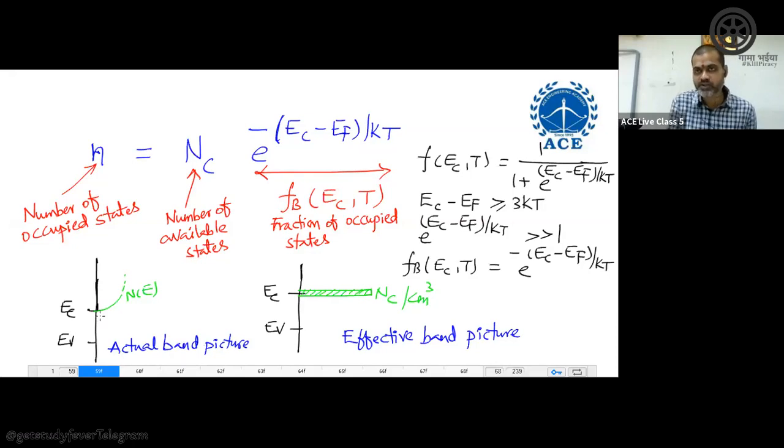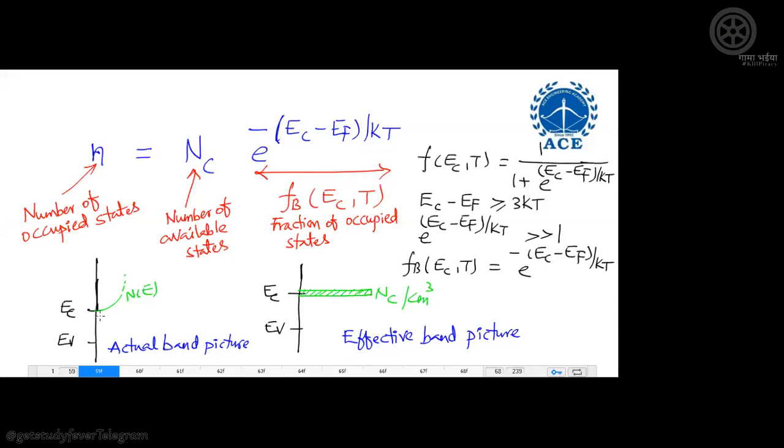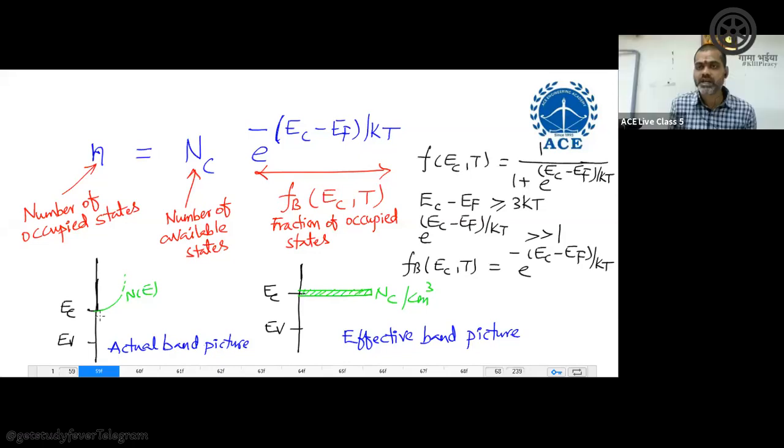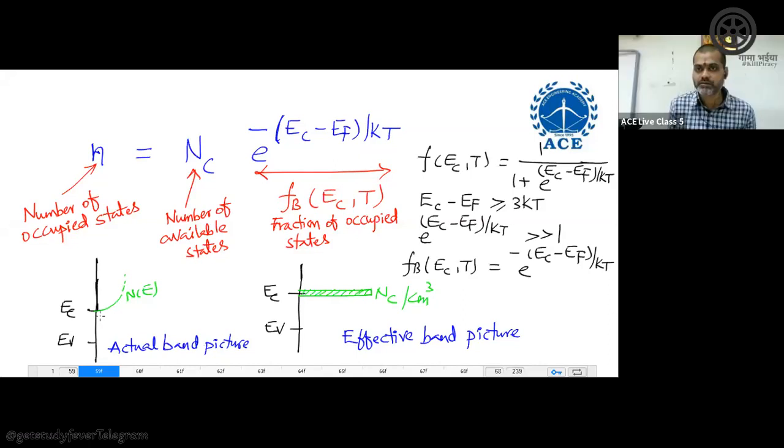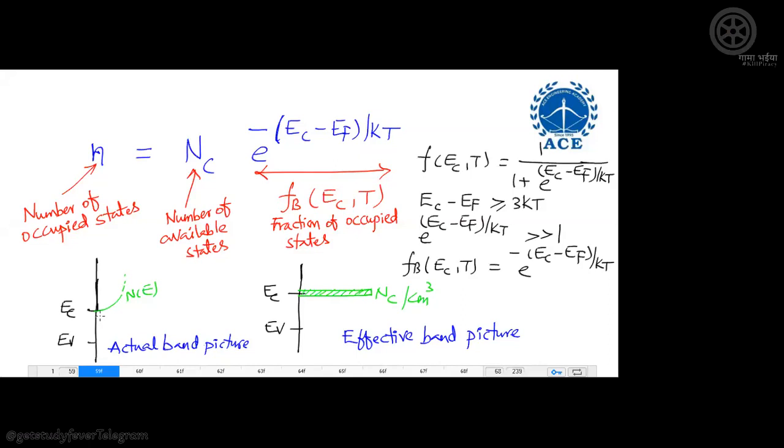Later we are going to take the numerical value also, since we still have not completed the Fermi energy level location. Theoretically I have explained. Take silicon as an example. What is the energy gap at room temperature? 1.1 electron volts. Am I correct? 3 kT means what? kT is 0.026 into 3. You compare EC minus EF and 3 kT. Yes, it will hold. Okay? Thank you.